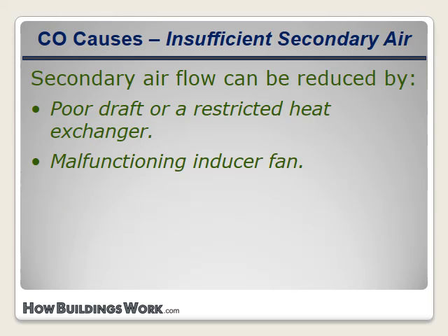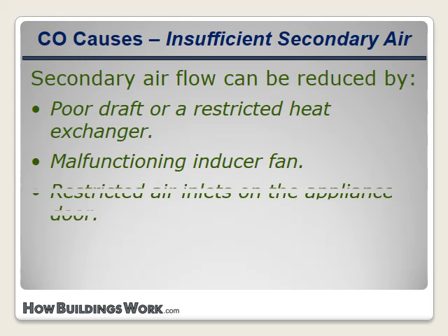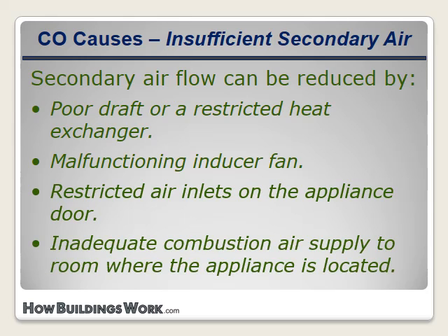In addition to draft or inducer fan problems, insufficient secondary air can be caused by obstructions blocking the air inlets on the cabinet or door of the appliance. Another possibility is that the space the appliance is located in is too small or too tightly sealed to feed enough air to the burners.